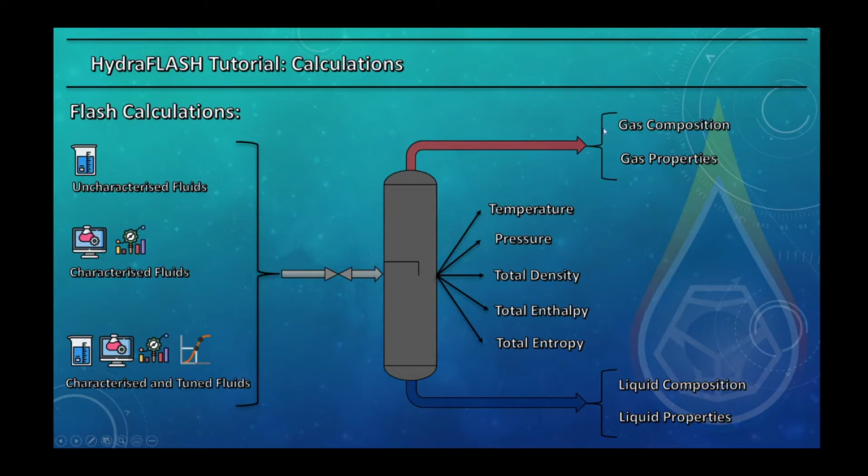So what you will see in the oil and gas industry a lot is a flash drum, a vertical two-phase drum. In this drum, a fluid, an oil or condensate, flows through this pipeline and then passes a throttling valve. The pressure drops, and then the two-phase fluid enters this flash drum, and then the vapor goes from the top of the vessel, and the liquid is extracted from the bottom of the vessel.